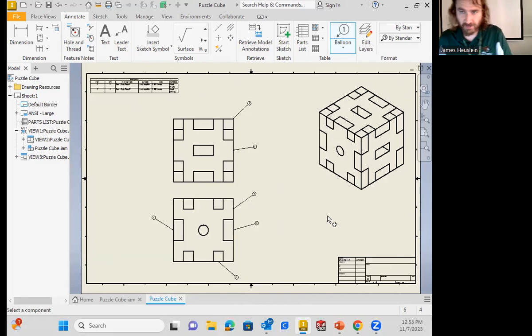That is the most challenging thing about doing any type of assembly drawing. It is labeling the parts, okay? So you got to find them all. Again, you can leave your mouse cursor there for a certain amount of time. Again, it should pop up what that object is, what that part file is. There it is. It pops up right there, right? And so if you're having trouble identifying what pieces are what, Inventor can help you identify it by letting the mouse just rest for a moment on that position, and eventually it'll pop up and tell you, right, what those pieces are.